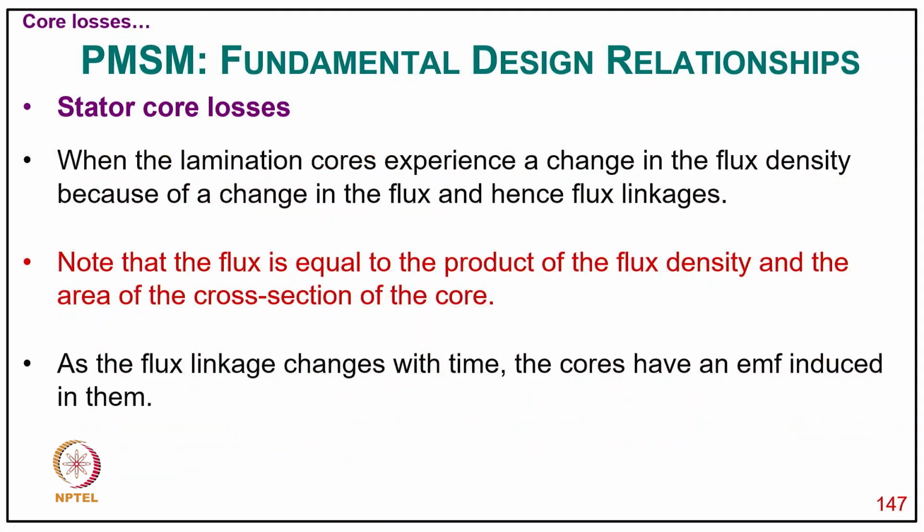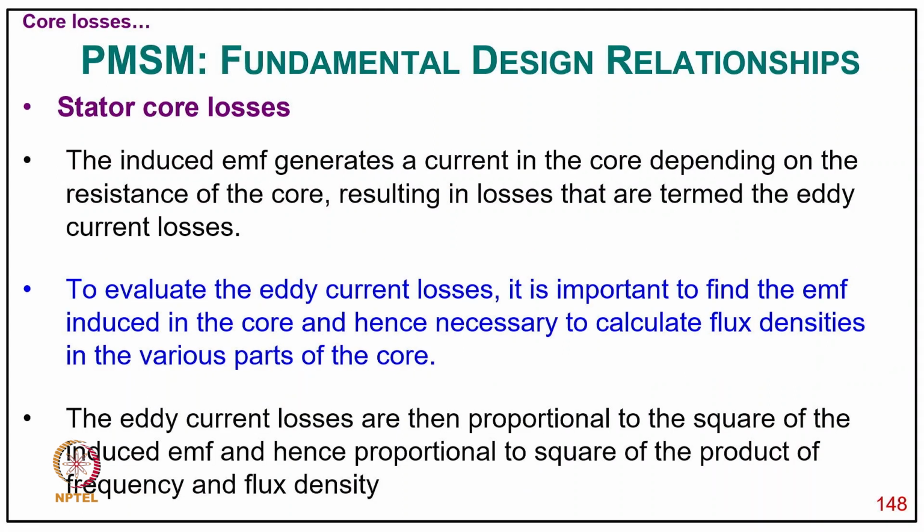And when the laminated core experiences a change in the flux density because of a change in the flux and hence the flux linkage, note that the flux is equal to the product of the flux density and the area of cross section of the core, and as the flux linkage changes with time, the cores have an EMF induced in them.